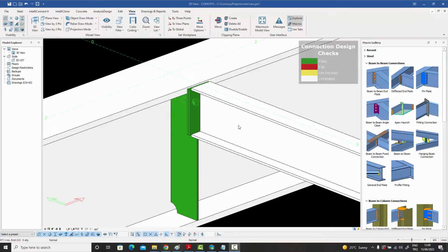It'll just do 2 or 3 major checks. Like what it'll do is, let's say the shear force on this is, say, 5 tons. So it's going to just go and check. It's going to take a rough guideline number for the shear capacity of these bolts. And the reason why I'm saying a rough guideline number is because when you actually go to the code, like I said, it might dictate several conditions. That in this condition, you modify it by 10%, or you increase it, or you decrease it, or you take a different value. But in the preliminary design, it doesn't go through all that. It'll just take a suggested allowable shear value for the bolt and do the basic number of bolts check.